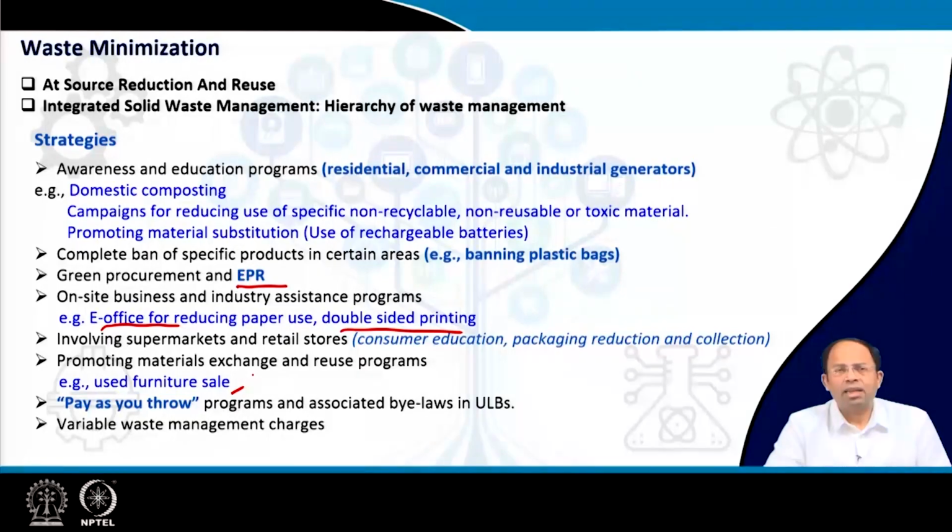So that is how you can promote exchange. And then the other two aspects that ULBs can also take, these are more prohibitive ones. That means they can institute a pay-as-you-throw program. That means the ULB can create some laws or bylaws which say that if you throw this quantity, you would be charged this much. If you throw a bigger quantity, you would be charged at a much higher rate, right? Similarly, if you throw certain kinds of items, you would be charged extra for those items. For example, construction and demolition waste, I can charge extra because this waste weighs a lot compared to normal residential waste and so on.